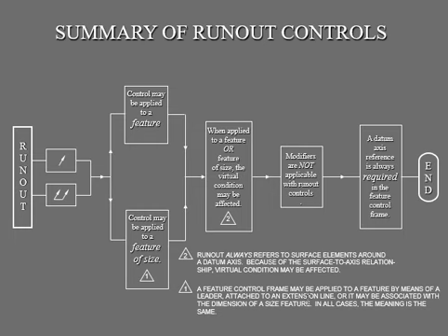Your little one row table has to be applied to a feature by means of a leader. We always put a leader to show where your tolerance is applied, and then it is attached to the extension line. We know that all the time. Or it may be associated with the dimension of that size feature. So in all cases, the meaning is the same anyway. Then we will take a look at when applied to a feature or feature of size like this, where you will decide circular or total.